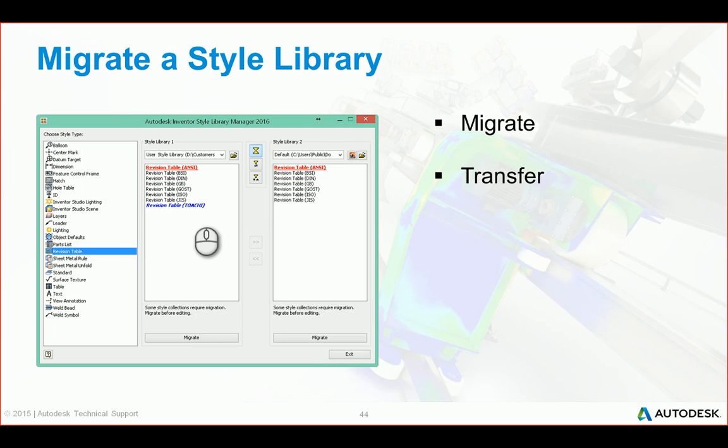First thing I do with my design data is I take that folder and I zip it up, just in case. That way I have factory default design data. Then, if I've got a shared one up on the network, I'll create a 2016 and put it up there.